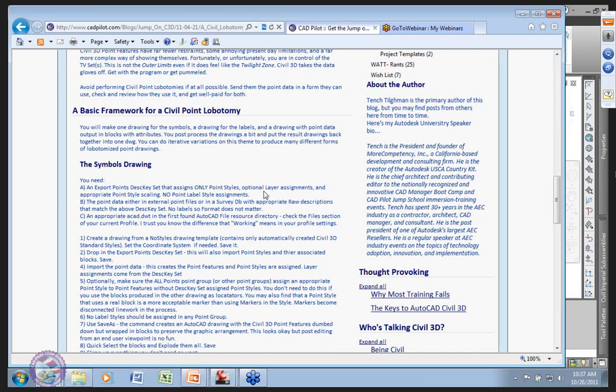They are now meshed together in this thing called the point feature, where the label, the symbol, and the data that underlies them are all tied together in a wrapper. They're all bundled together into this thing that I can do all that wonderful changing to. But when I dumb it down to AutoCAD, I have to get down to the dumb block and just the mtext.